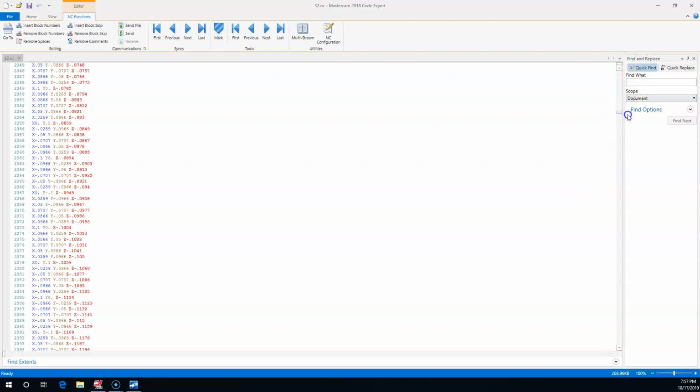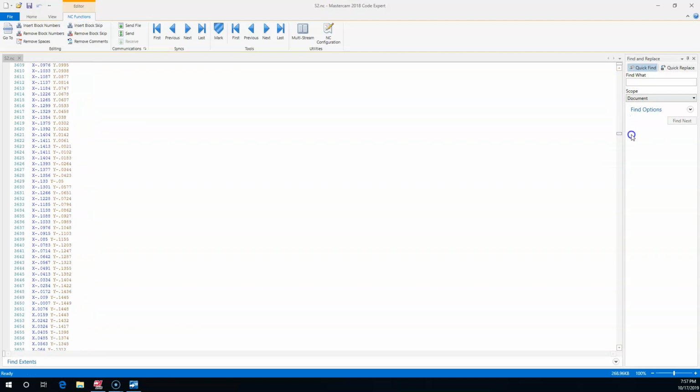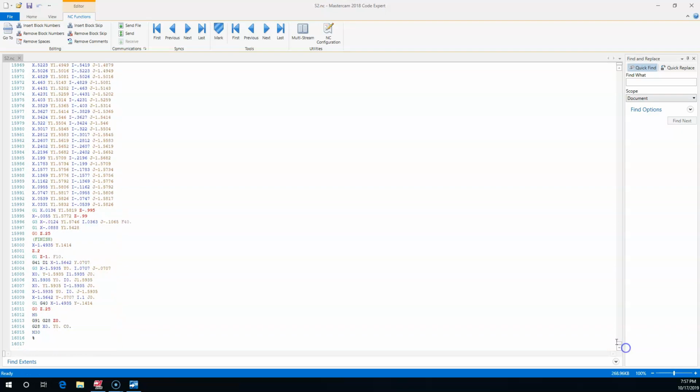All right, so right now there's no end numbers, so in the control definition, when I turn those off, that is working. If we're generating this much code, I don't need 4 additional characters at the beginning of each line, and it's not really going to help me that much anyway. Does the finish, so we're seeing each of the definitions where I put those comments in, those are showing up. And G41 going to depth, feeding in, feeding out, and then returning.